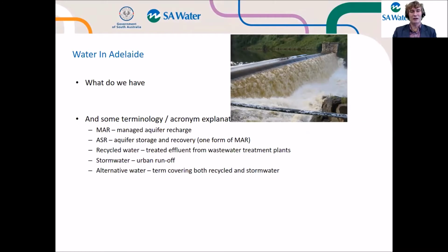So water in Adelaide: sometimes we have it, sometimes we don't, sometimes we have too much, and often we don't have enough. Some of the terminology I'll be using throughout this presentation: MAR, or Managed Aquifer Recharge, is just the process of getting water into the aquifer. Aquifer Storage and Recovery, or ASR, is the type of MAR that we do, and that is taking water, injecting it into an existing bore, into your target aquifer, and then drawing that back out again when you need it.